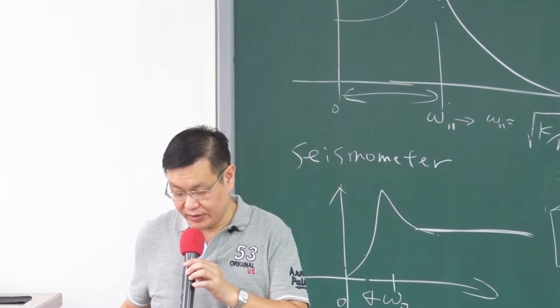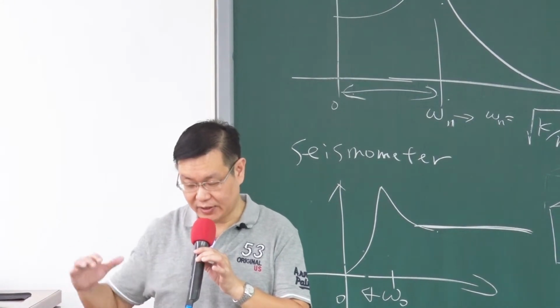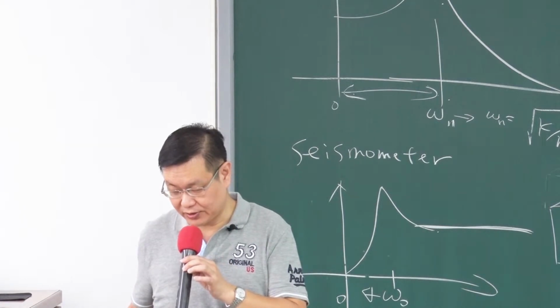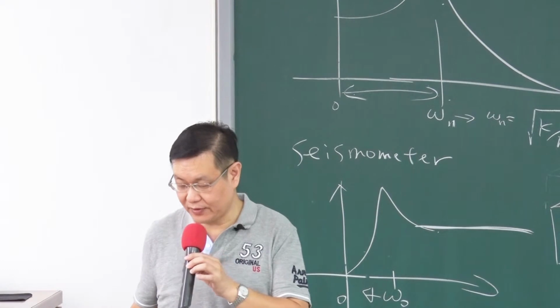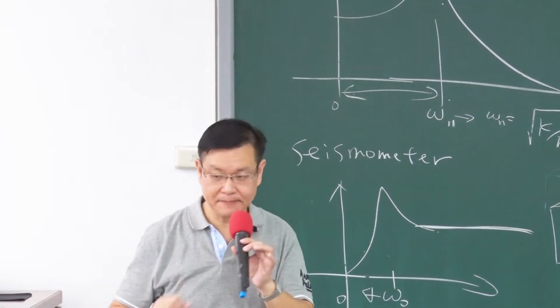So finally, we can see the curvature is proportional to the bending moment from the outside, inversely proportional to the material property, the Young's modulus, and inversely proportional to the moment of inertia. So if you have a large moment of inertia, you won't get a lot of curvature. Okay?